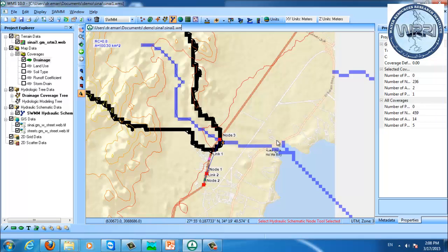Okay, but most of our work is not for rivers. Here in this institute, we are working on arid region watersheds, the wadis. Wadis, yes. So maybe HEC-RAS is not what you want to use. Really? So which module in WMS is the best for such a case? Probably GSSHA. Set up a GSSHA model for this area and you can get the depths and the overland flow.